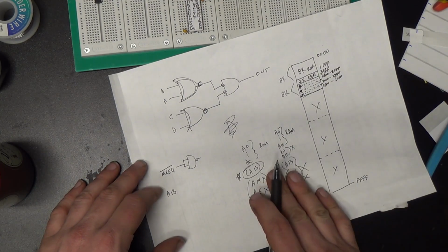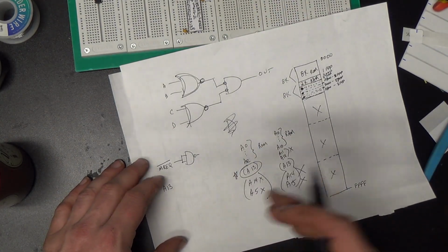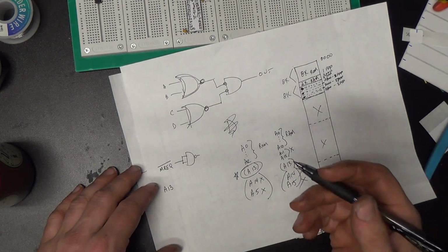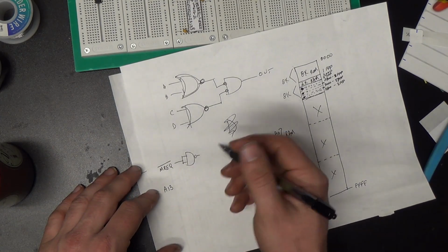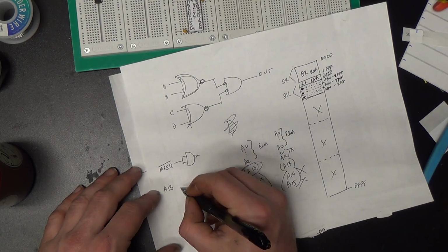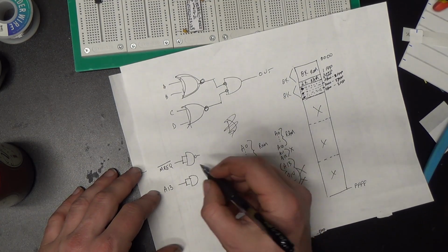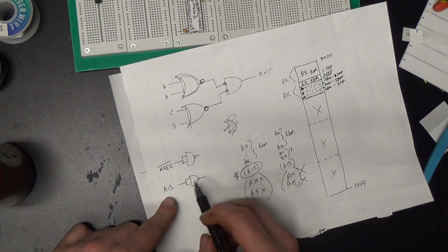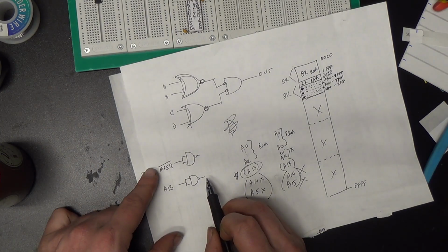Since the chip select on both the ROM and the RAM is also active low, we want to have a low output when that happens. Fortuitously, this is easy to do with NAND gates. So we'll put A13 through another inverter made out of another gate on this quad 2-input NAND chip.